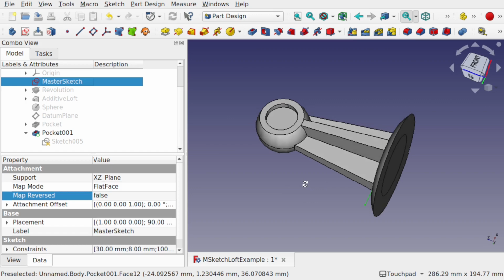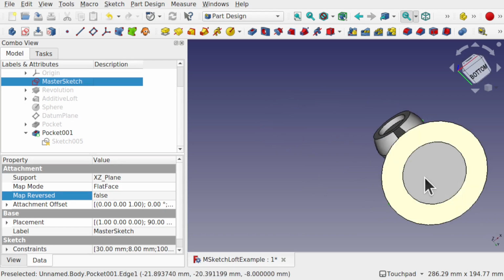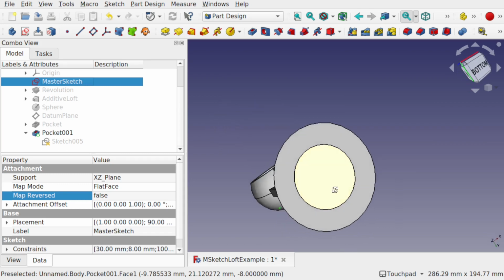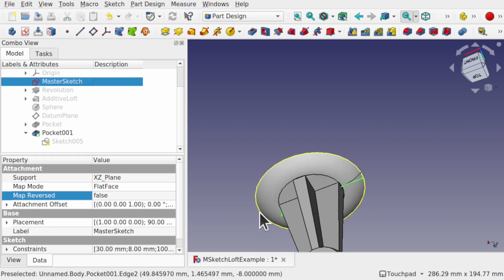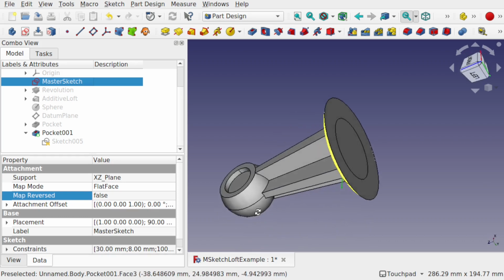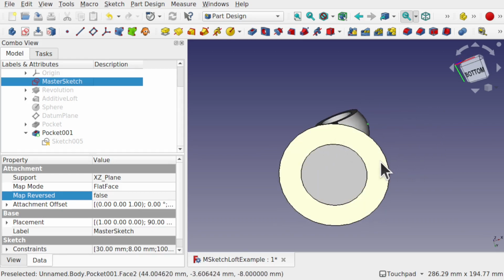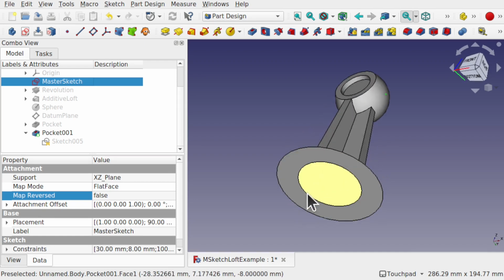So from this lesson, you've learned how to control a part design model through a master sketch, and also learnt about formulas or the expression editor. In our next video, we're going to be looking at hidden attachments in objects. So for instance, if I look at this object, if I wanted to attach this to a wall without showing, say, some holes that go around the outside here that have screws through, then I need to make a hidden attachment in the back. Now this could be some kind of slot or bayonet attachment, and we're going to be looking at how to create that feature in here, because we need to know how to model internal features.